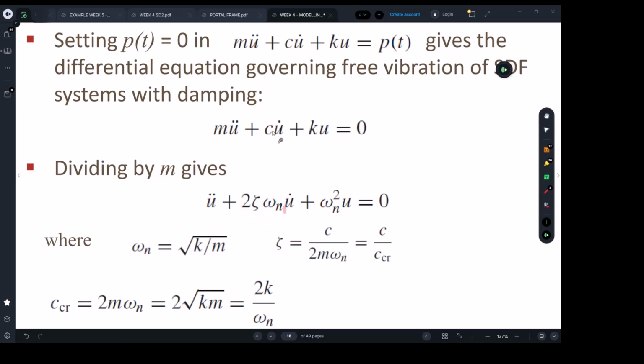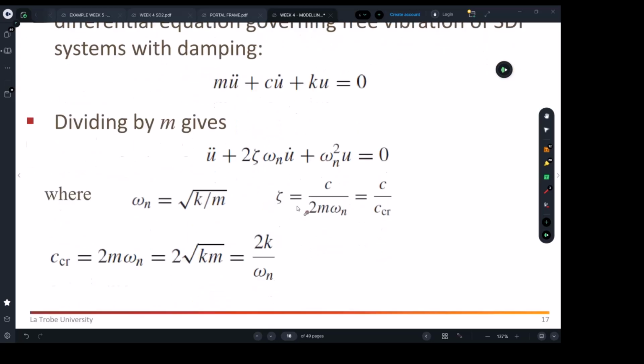They said C, basically, is in function of omega, so they can replace the C with 2 eta by omega, the natural frequency. Now, given that omega is equal to root K over M, right? Originally, to simplify it for you, this was in the equation, okay? And C is actually a function of the damping, okay? Now, to simplify things even more, this one is actually defined as you can see.